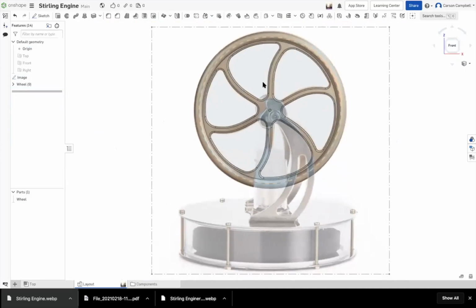And for this part right here, would I just completely start something new? Say I get to the assembly, I could just throw it in there and have multiple parts, or how would you go about it? I would put this whole geometry set inside of one part studio. But right now, this is where everybody's struggling: how many part studios do I want to create when I'm working on a project? You mentioned that, so that's why I'm bringing it up.